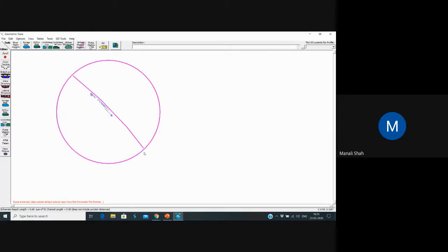Due to this reason, it is not required to bring the exact location of the Vishwamitri river over here. It is absolutely fine to draw it randomly with our hands, as we are working in one dimensional flow. If we were working in two dimensional flow, then it would not be possible to draw a river reach by hand. In that case we would compulsorily need to plot the original section of the Vishwamitri river over here for the modeling process.